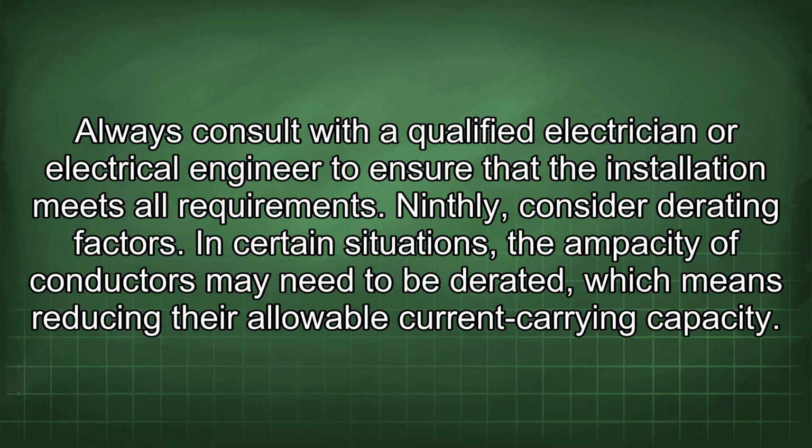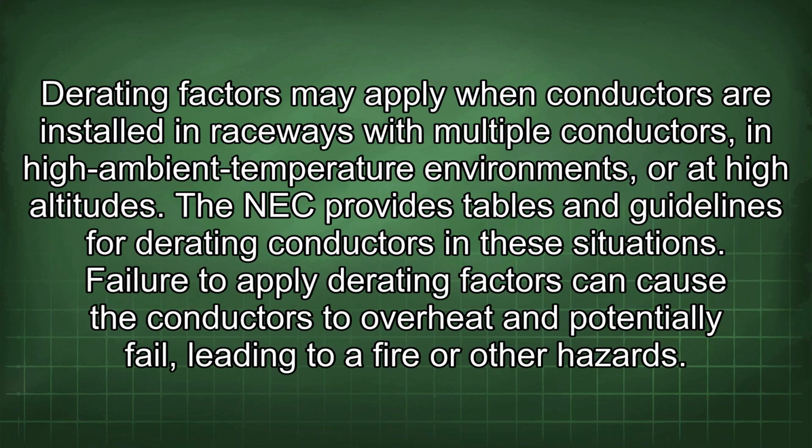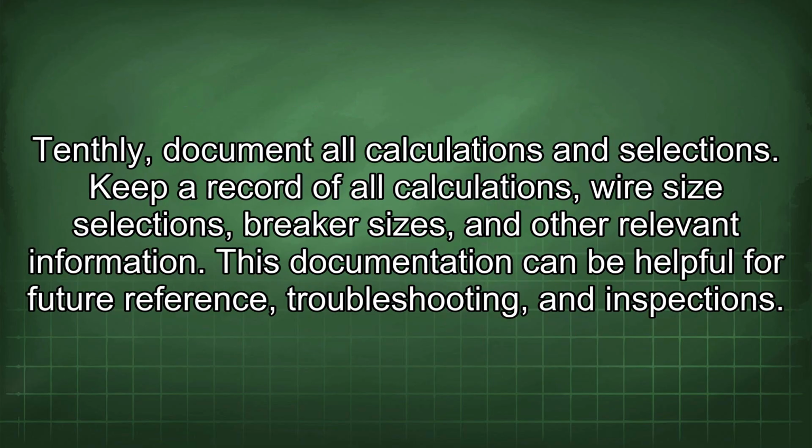9. Consider derating factors. In certain situations, the ampacity of conductors may need to be derated, which means reducing their allowable current carrying capacity. Derating factors may apply when conductors are installed in raceways with multiple conductors, in high ambient temperature environments, or at high altitudes. The NEC provides tables and guidelines for derating conductors in these situations. Failure to apply derating factors can cause the conductors to overheat and potentially fail, leading to a fire or other hazards.